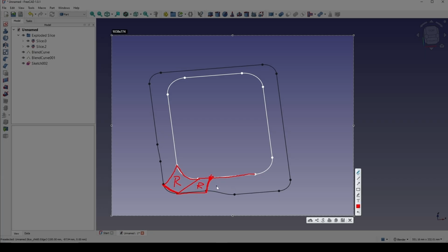Okay, so I will skip this hole. I should come over here and connect between this arc and this arc, so that I will have another rule surface. And after I have this rule surface, I have enough edges to fill using the surface filling in the surface workbench to fill this hole.